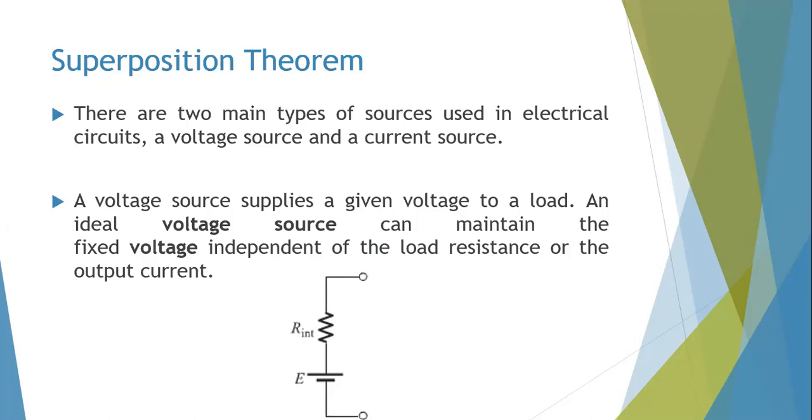But what happens when your battery starts aging, and it starts not being able to provide voltage? That internal drop across its internal resistance becomes higher and higher. This causes your battery to not provide 12 volts; it can start providing 10 volts, 9 volts, and this means maybe your injectors or other elements in your car cannot even operate because they need 12 volts. Yep, so this is one example.